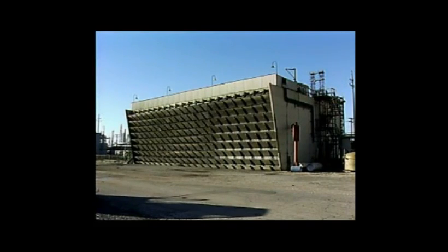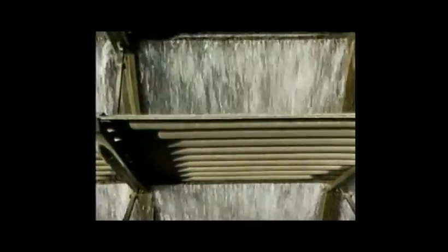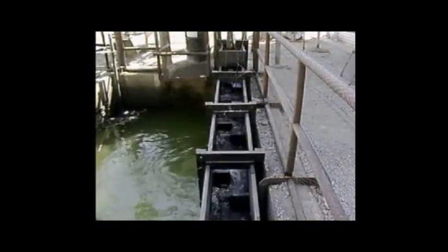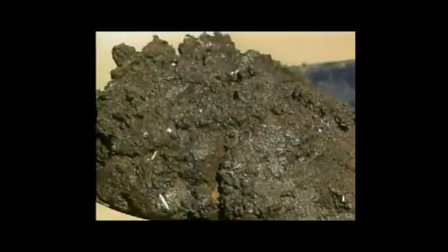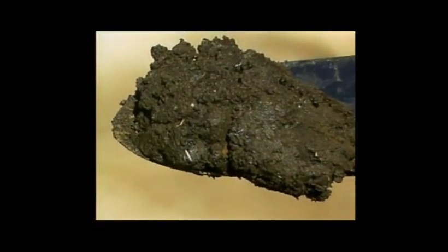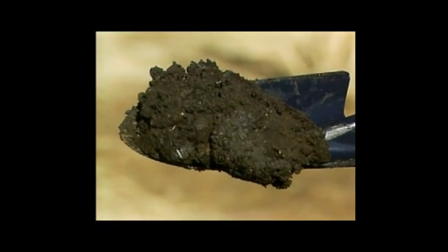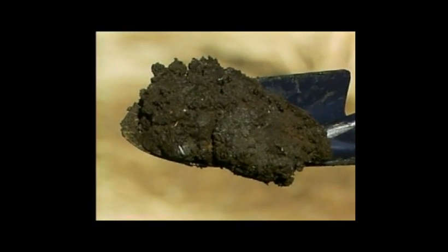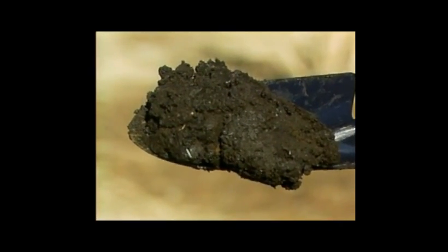One source of these particles is air. Dust and dirt can be carried into the tower by the air passing through it. These particles become trapped or suspended in the cascading water. Another source of suspended solids is the makeup water. Solids are carried into the tower as water is replaced. When suspended solids collect inside a cooling water system, they form a thick mixture called sludge. Sludge can restrict water flow through equipment, interfere with the transfer of heat, and decrease cooling tower efficiency.